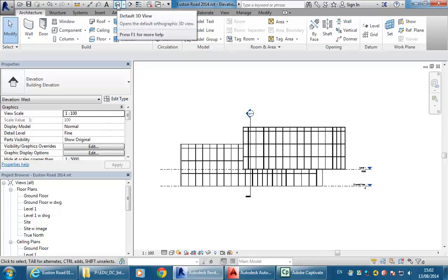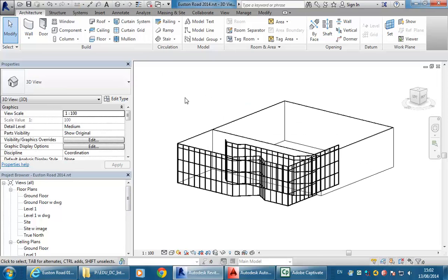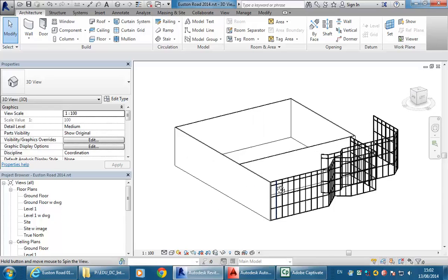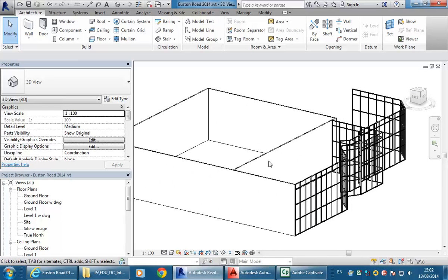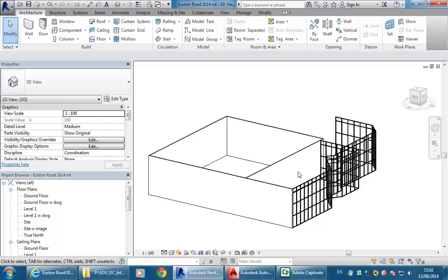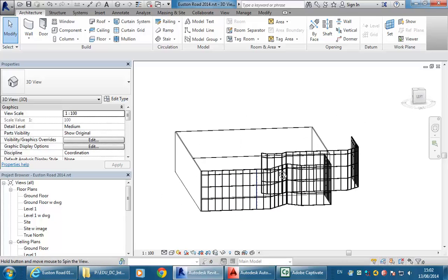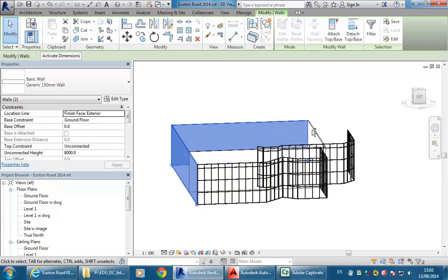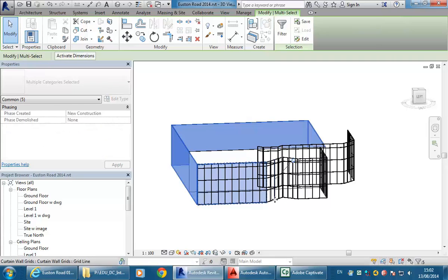Now I'm going to go into my 3D view and start tying the walls to those levels. So you can see there, as I made the walls earlier, I didn't think too much about the levels. And that's fine. Normally you'll start projects that way. So right away I can choose these outer walls. Just using control, I'll select all of them. Oops. So if you've got curtain walls, make sure you get the outside of the wall, not a part of it.